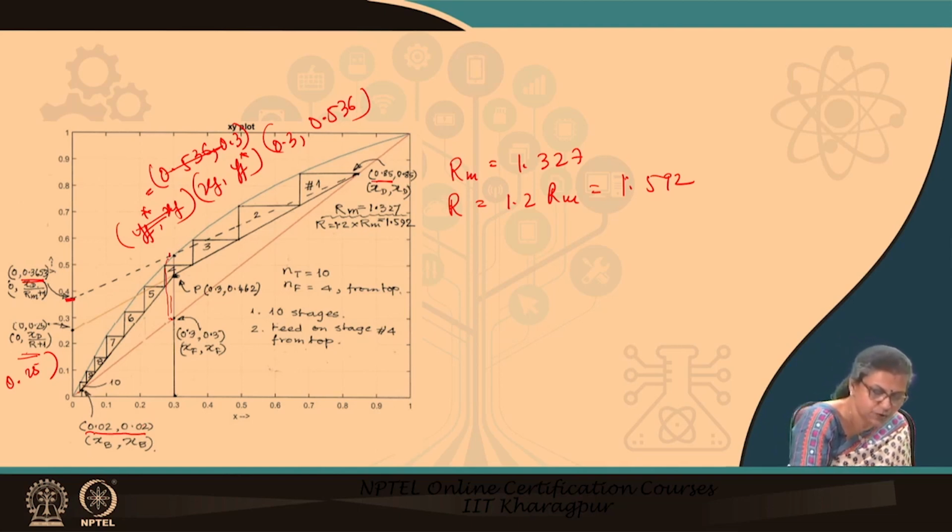So, xB is 0.02. From here we extend the stripping section operating line. Once we have done this, now we start dropping the number of steps. Please do it yourself. You will find that in this particular process, more or less, we have 3 trays in the enrichment section.